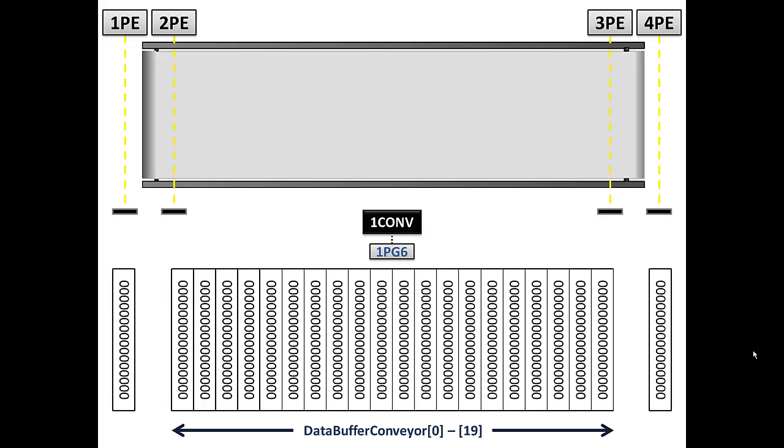So if it puts out a pulse every 2 inches and we put out 6 pulses, we know the belt has traveled 12 inches. The actual inches traveled per pulse doesn't matter for our illustration. It would in the real world, because you would have to pick your pulses per foot or inches per pulse, however you want to describe it, based on your carton size and length of conveyor.